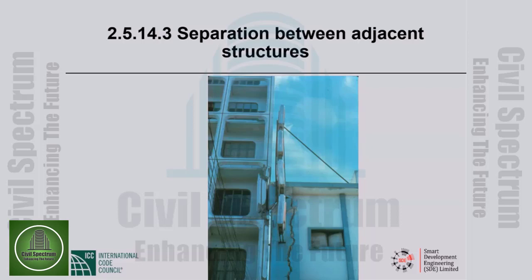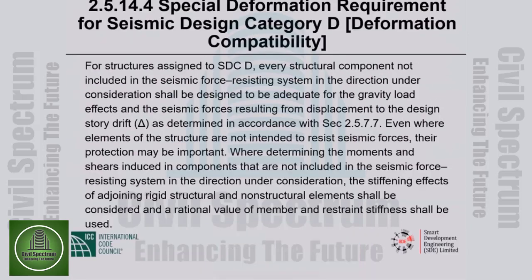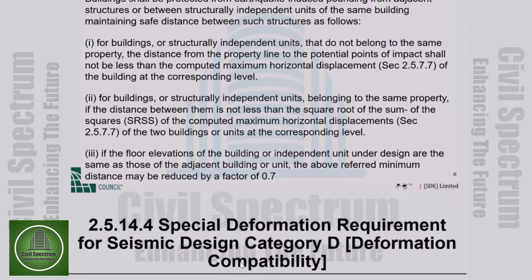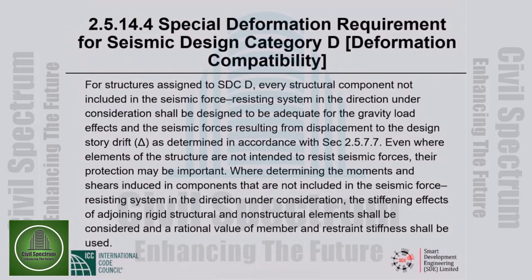Okay, so that does justify a decrease in separation distance, and this 30% probably is pretty sensible. So I kind of like this addition that BNBC has made to ASCE 7-05 requirements.